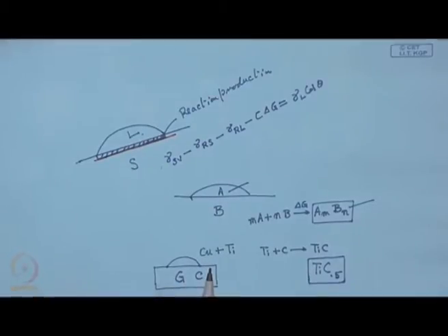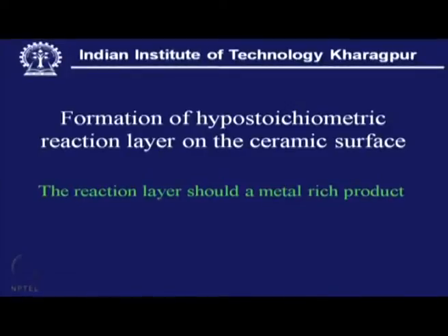So, this is exactly what we mean by hypostoichiometric reaction layer formation at the surface, and this is the sufficient condition to promote wetting.